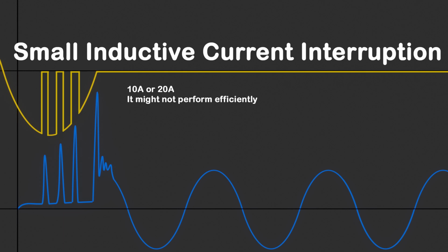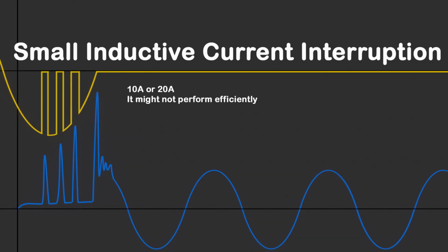When the dielectric medium between the contacts breaks down due to arc formation, and the short-circuit current waveform naturally crosses zero, the breaker applies deionization force to quickly re-establish the dielectric strength between the contacts. This ensures that the current does not restrike after zero crossing. That is, the arc does not reignite. This process is applied in high-voltage circuit breakers to break short-circuit currents. The capacity to do this is called the short-circuit breaking capacity of the circuit breaker.